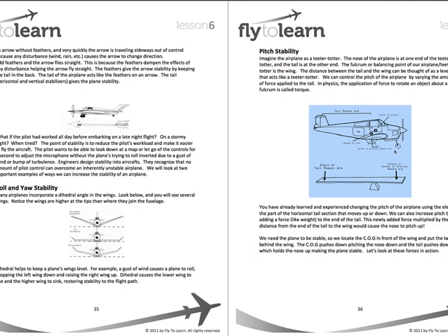And just like on the teeter-totter, you're showing the fulcrum. So the fulcrum in this case is the wing. I'm willing to bet most pilots think the fulcrum is the center of gravity. And anytime you see this in aviation, they almost always just do weight and balance problems, and people will learn to do the problems, but they really don't understand what they're doing. And this didn't come from me. This came from the CFI folks that are interested in this.